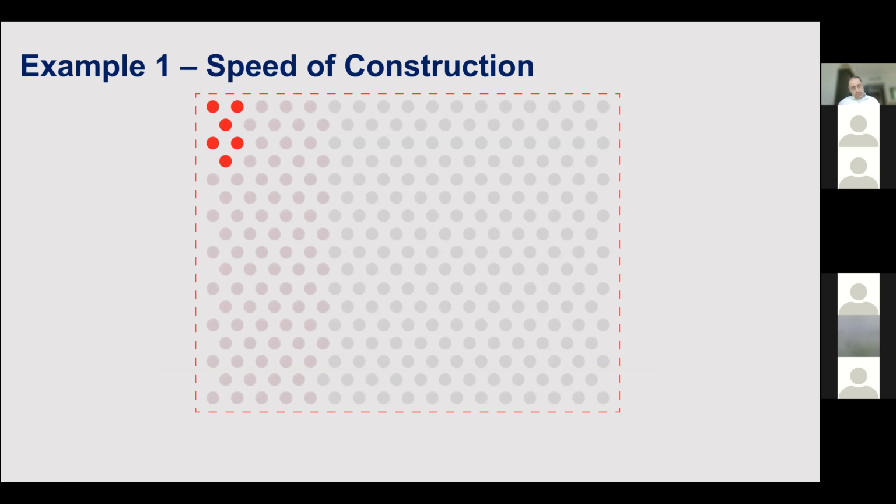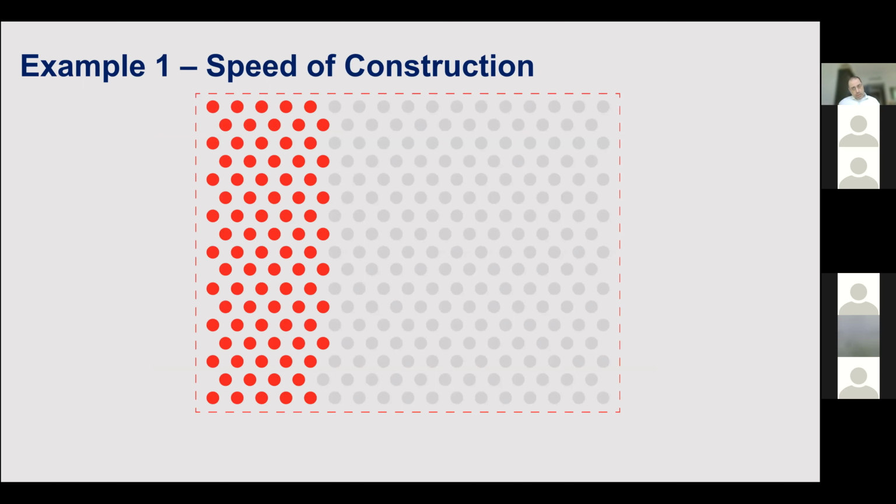Now compare this with this number, which is the number of piles that would have been installed had you been testing using a different method. Maybe close to a third of the piles would have already been installed, and there's something inherently wrong in the installation process, and you will not be able to catch it until you've installed that much, and until you receive the report from the testing agency.